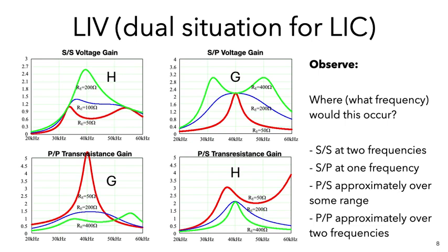In this particular page, I'm showing you the LIV conditions. For example, the SS compensation circuit. Here we identify this point and this point where the voltage gain remains unchanged irrespective of the change of the load resistance. So for different load resistance, this point and this point basically overlap. In other words, the voltage gain is constant, so that's the LIV condition. However, for this SS condition, we realize that the efficiency is not optimized.